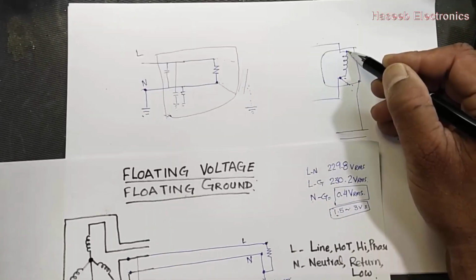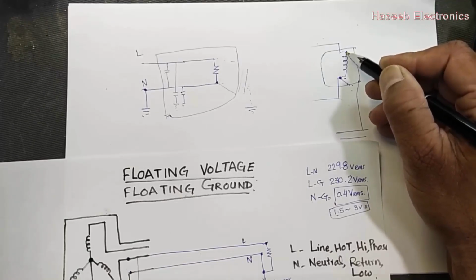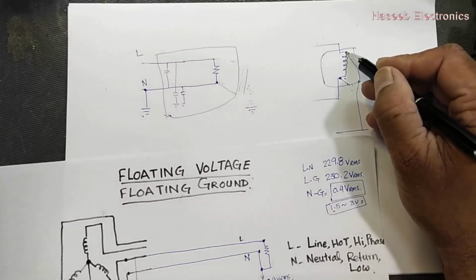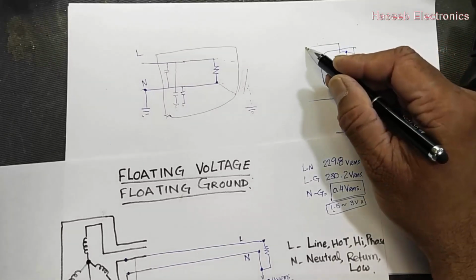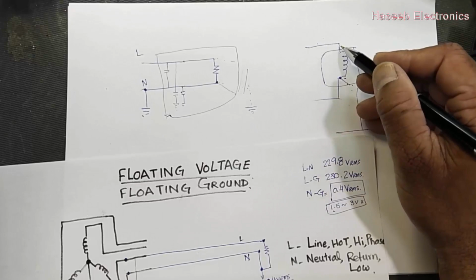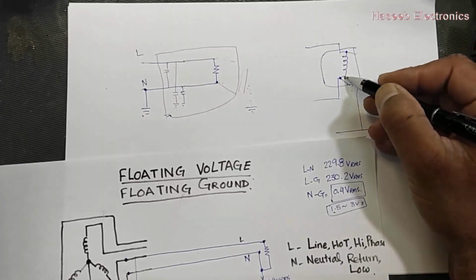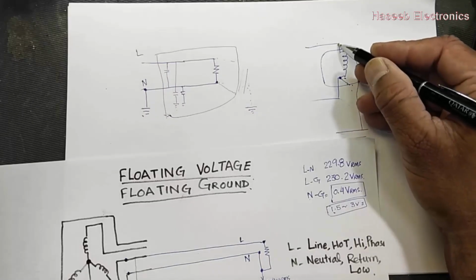But in the second condition, if this end of the winding shorts with the core, the phase voltage, the line voltage, the hot wire will leak into the body. So we have winding two ends. It is the entrance.